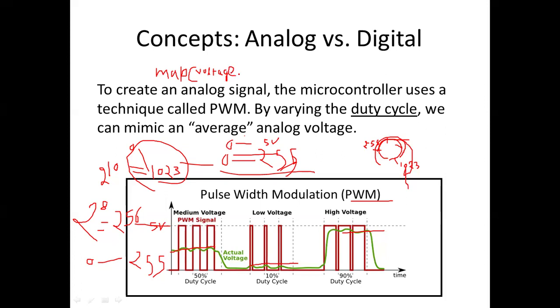First of all, we have to define the voltage value range. So my range is 0 to 1023. We have to use a comma over there, and the range goes 0 to 1023. Then after that, you can see the range, that this one is the conversion. So the conversion we want to do is 0 to 255.